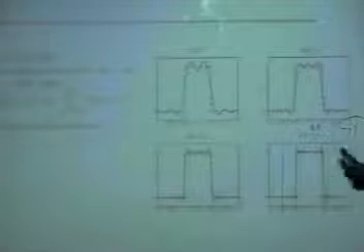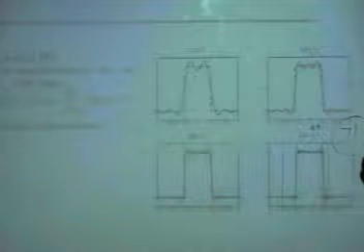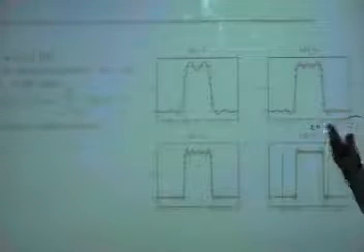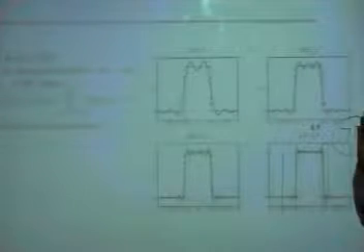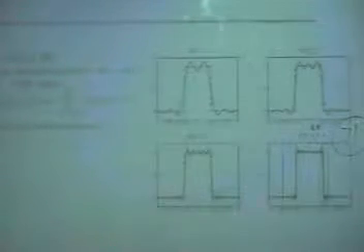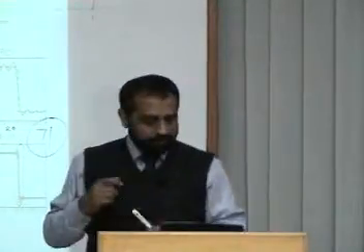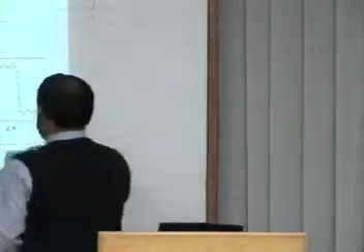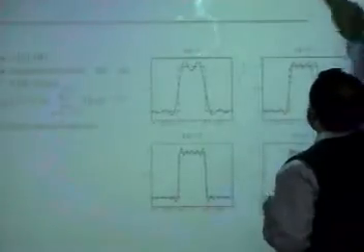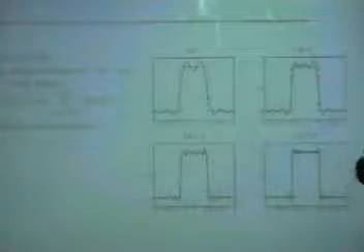That's how, once they publish, the judges say, look, I have devised this technique to design a filter which takes only this many samples and gives you better results than what you otherwise get from the crudest way, just chopping off the sinc. That is the crudest. Obviously that is the crudest, if you did nothing and just took these many samples. But there are several techniques, which we will learn about, that say do this, do that, and they help you design an FIR filter. It's a finite impulse response because of the finite nature of the impulse response.